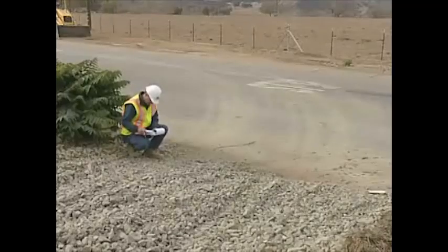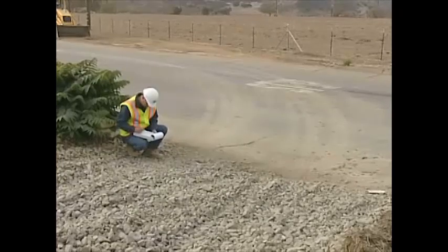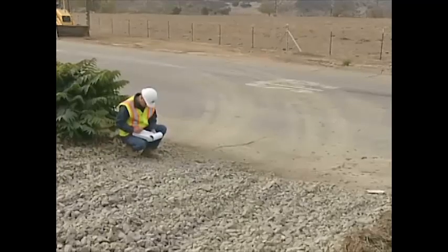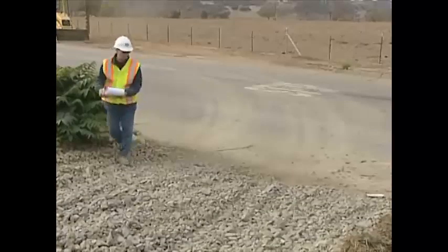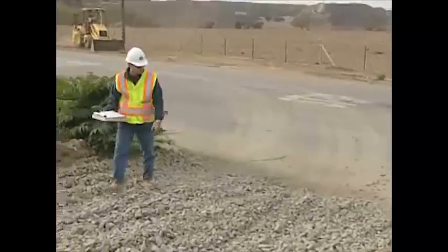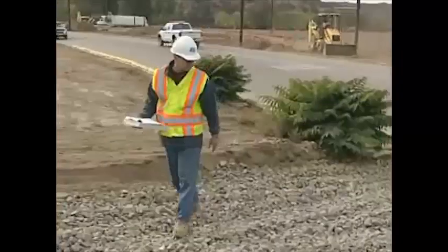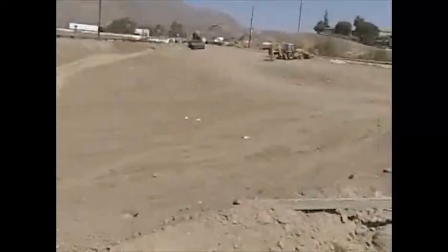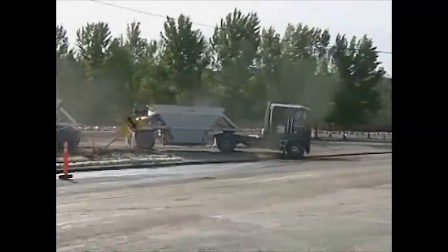These activities reduce the tracking of sediment from construction vehicles onto public roads. This best management practice should be implemented at construction sites as a preventative measure to minimize the tracking of soil onto public roads in areas where the site is adjacent to a water body, where poor soils are encountered, and where dust is a problem during dry weather conditions.